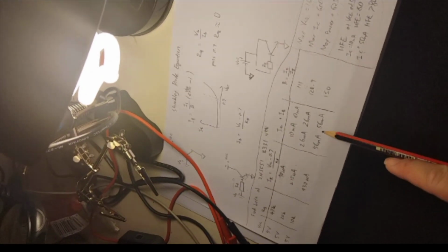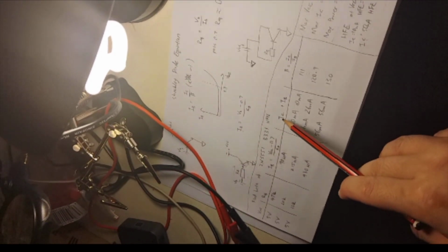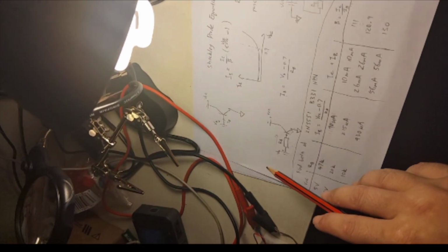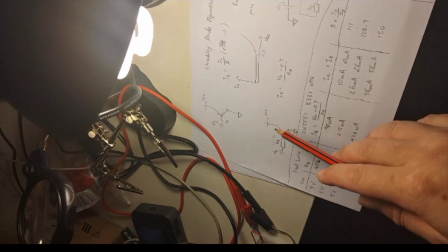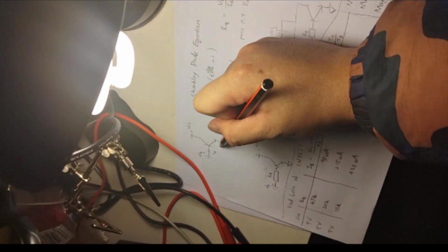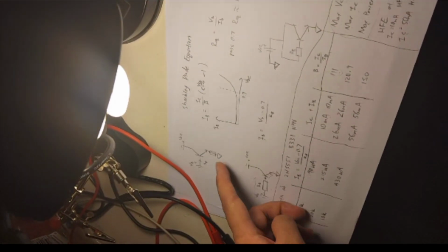So this transistor is doing what it's saying it's doing, but as you can see, the beta varies when you have a different current. And this is as expected of an NPN transistor, which is why when actually using the NPN transistor, because the gain is so different, you cannot use the base voltage alone to determine the collector current. You have to use something called emitter degeneration, which adds a resistor onto the emitter. And that's a demonstration I'm going to make another video for.